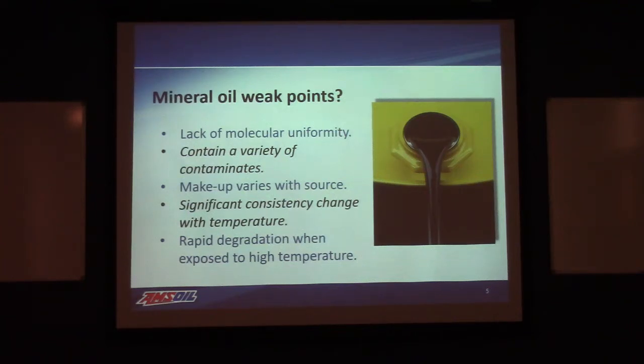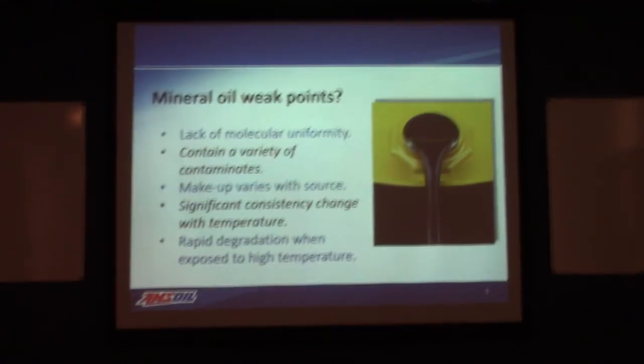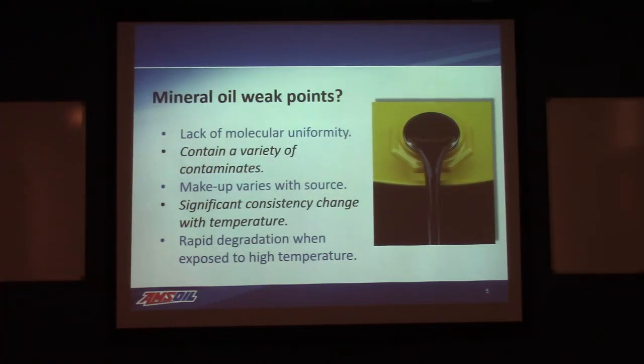Plus, too, when we look at mineral oil, it comes from crude. Depending on where it's obtained, its molecular makeup is going to vary. So again, its ability to address issues is going to change, all depending on where it came from. Was this some Texas sweet? Did this come from Saudi Arabia? Is this from the North Sea? They're all going to be slightly different, slight variations in there. And they do have a tendency to degrade at significantly lower temperatures, okay? With the issues that the new equipment are being faced, this is a real detriment.